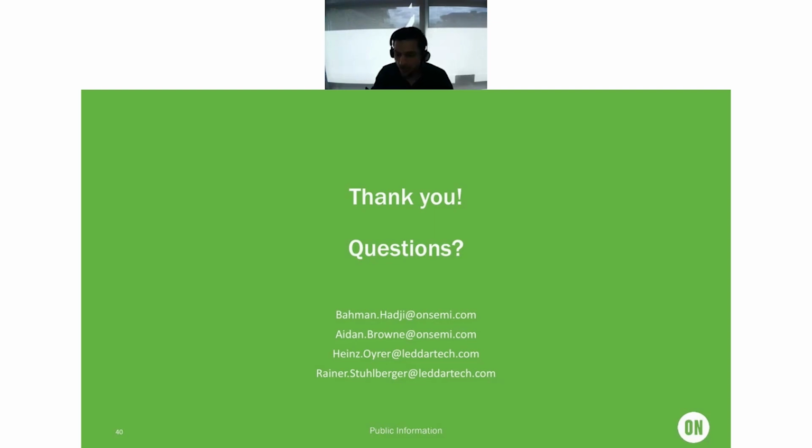Thanks, Aidan. I think the one other thing I'd add is with respect to the optics, the sensitivity of the SiPMs means that you can use smaller optics and lenses for cleaner integration into the LiDAR modules that might go into the vehicles. That's correct. So SiPMs can be used with a narrower angle of view, smaller apertures, so you don't need as large a hole in the system. So it can also be used to enable smaller, more compact LiDAR systems.